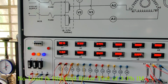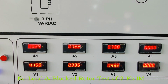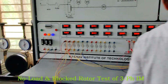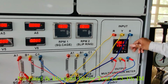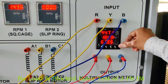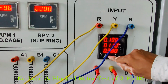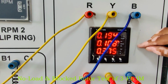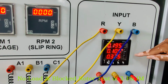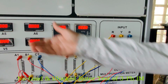At this voltage, we will take the readings 0.9, 0.7, 0.7, and this is a multifunction meter. This multifunction meter measures the wattage. There are 3 wattages, and suppose you have to take its power factor. The power factor is 0.19, 0.19, 0.3. So we will take the readings of power factor, power, line current, voltage.